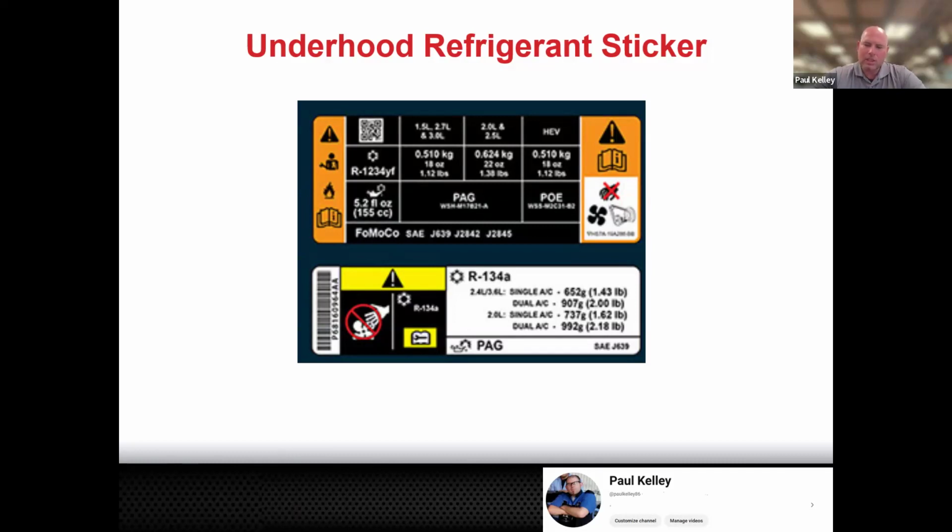All right, so deep, deep, deep in the service manual, it'll actually explain to you what you should do. If it has a leak and you don't know how much oil's in there, technically what you're supposed to do is recover the system, drain all the oil out of the entire AC system. For example, there's going to be a little bit of oil in your evaporator. How would you get the oil out of the evaporator? Well, it's behind the dash.